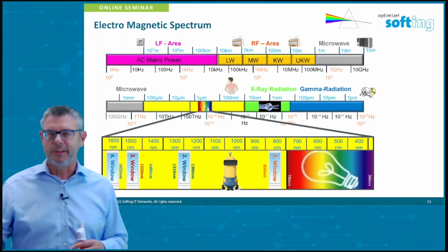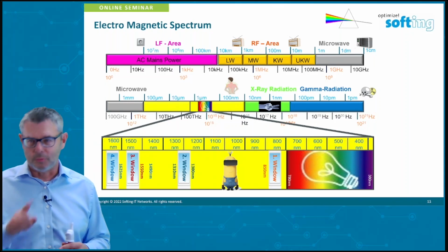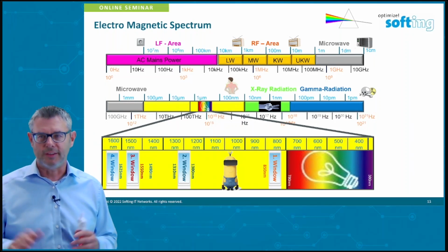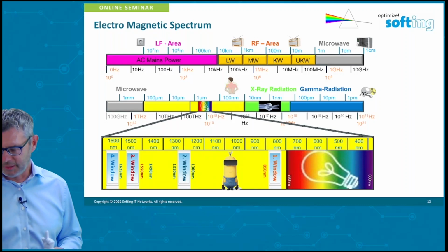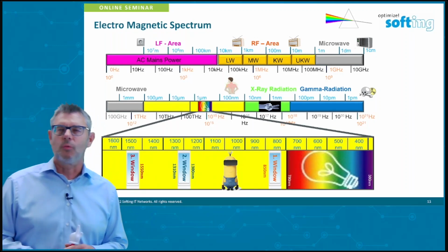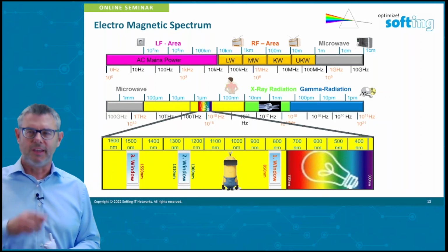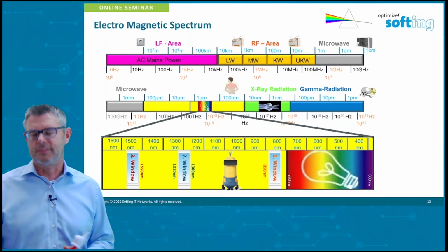Nowadays, the windows are opened up to the higher wavelengths. So the fourth window has opened up, and some windows in between are used now for dense wave multiplexing, all these fancy things. Let's reduce it back to these three windows we know. Why have we chosen these three windows? Because these three windows fit very nicely into the attenuation performance of glass.